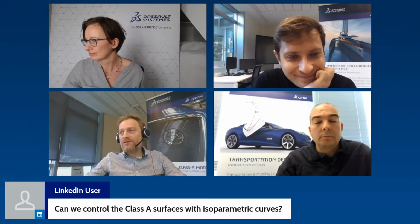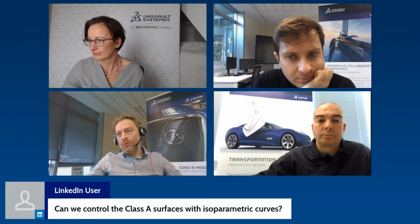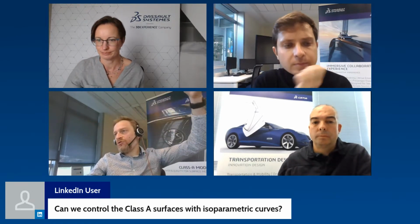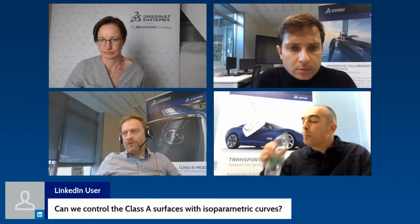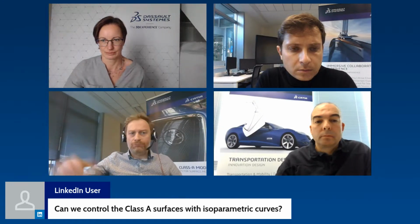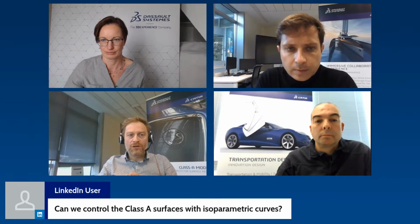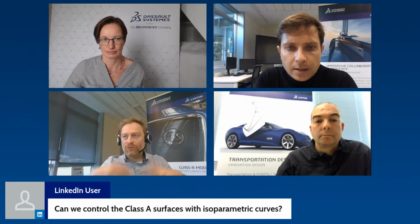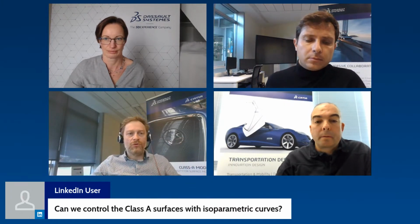Yeah, just to explain, in my example, it's not exactly an isoparametric curve. You could have done one. But what I did in the video is create on the fly one very accurate curve that I can model before, and then at any time I can inject a new curve as input. It was not an isoparametric curve, but of course you can do it with one. You can create an isoparametric curve and inject it as a new input curve, as a profile.